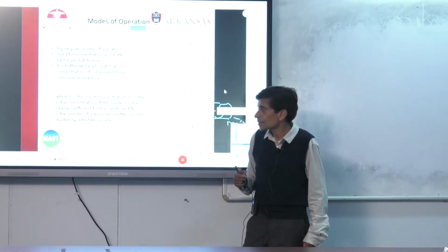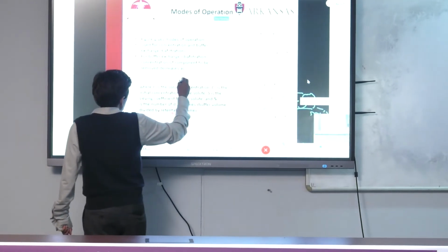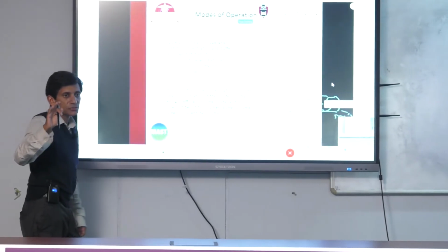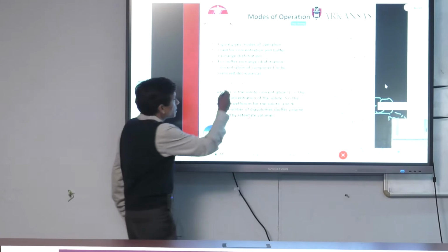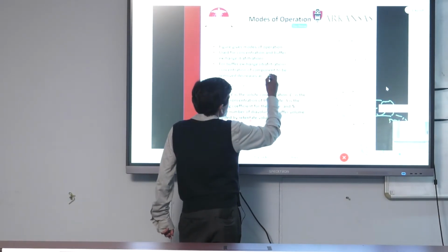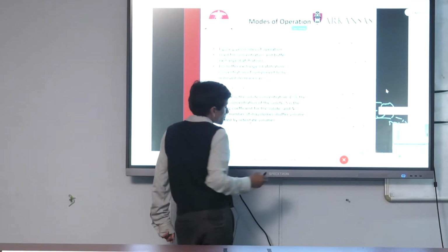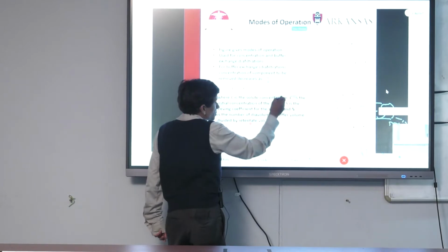All right? So if we assume that the sieving coefficient is 1, in other words, everything is going through, there's no rejection of what you want, and this is just an exponential decay, right? Like this. C divided by C naught versus N here. That's all that is. And you have 1 diavolume, 2, 3, and so forth.